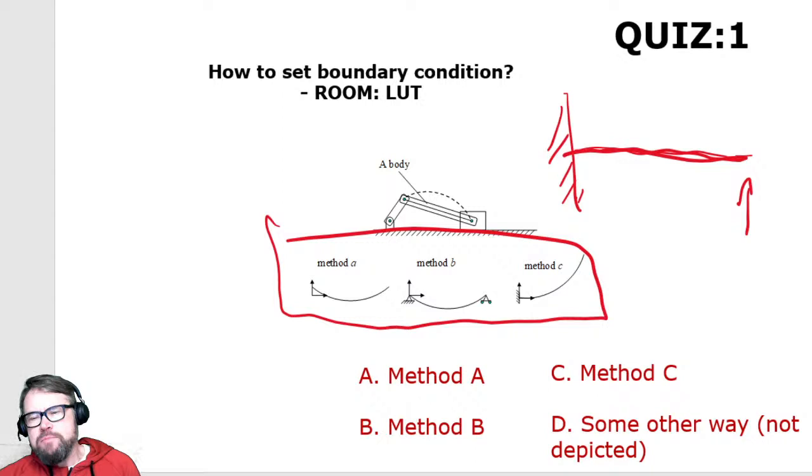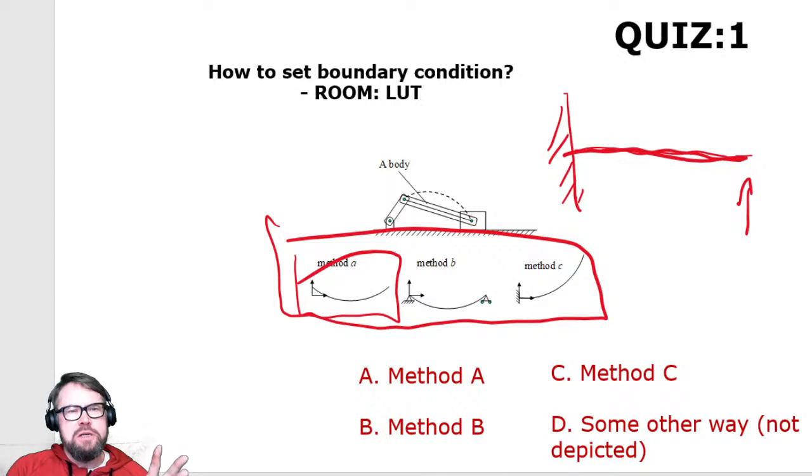In the first set of modes, my reference coordinate system, which is the coordinate system that I'm using in my finite element modeling, is left such that it's not attached to any material point of the structure, or of the model to be more specific. So it means that I have no boundary conditions here.